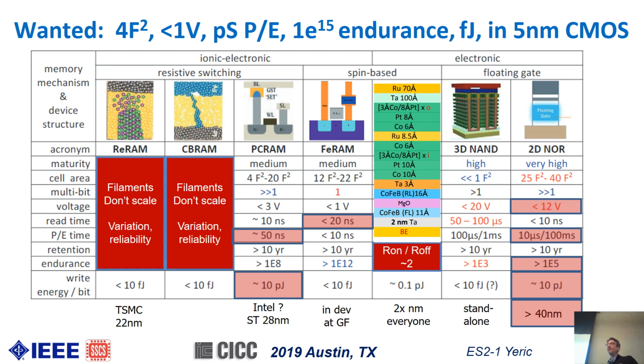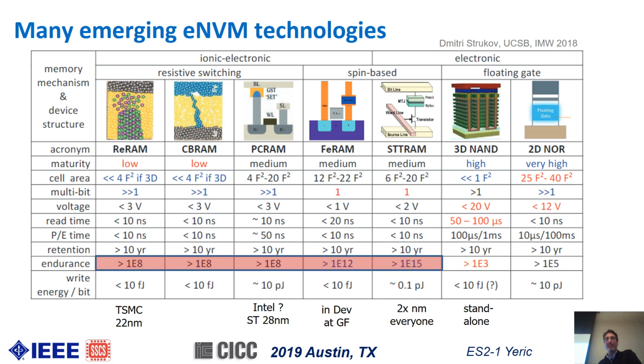And the other thing I'll mention too is it's not that robust in addition to the resistance. So when you actually look at a memory instance of MRAM, it's not 1 or 2% ECC. It's 25, 30% ECC. It's a messy technology. But if you do it right, you do actually have a pretty good memory. The one thing you'll notice with all these technologies is none of these numbers are infinity, which is what we would like as a designer. We want infinite endurance, and then we can just use it and not worry about it.